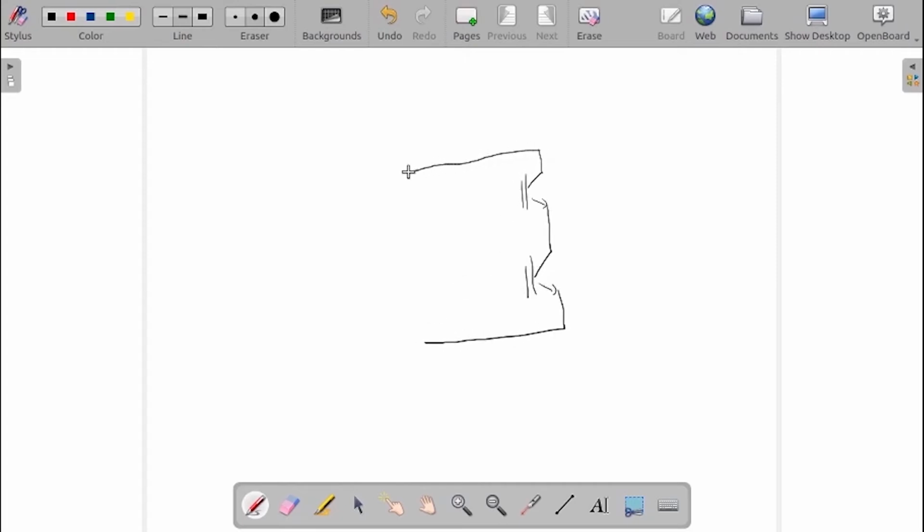Okay, so this is the DC supply. Now we have to give a gate pulse here at the gate of this switch T1 with respect to its source. So this is S1 here, and you have to give a pulse here, which is of course complementary to the top switch pulse, to the gate of T2 with respect to the source of T2.